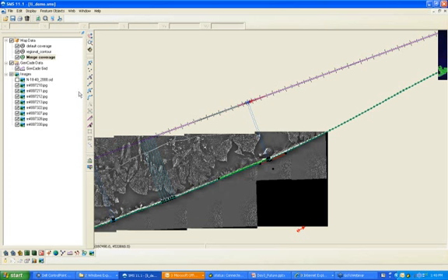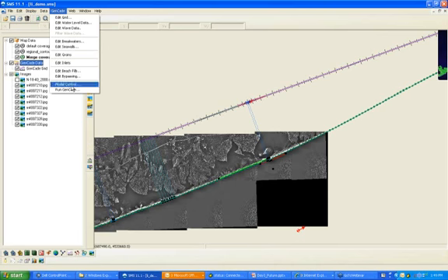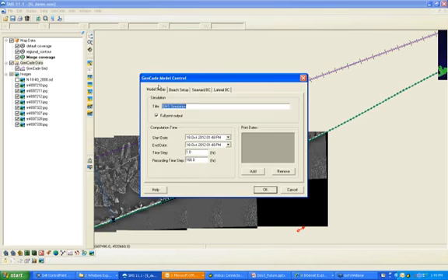So if we keep this as our case, we can go ahead and go to GenCade Data, and we're going to specify all the information. So we'll go GenCade to Model Control and enter everything for this case. So first, we're going to start and enter our start date and end date. We're going to start it at the 1st of January, and it's going to be 1983.